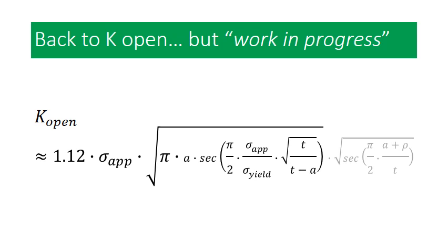Now, if you're familiar with my gamma exponent model, if you have a crack-like flaw, you're going to maximize your gamma exponent at 1, but if you have a corrosion flaw, a metal loss flaw, you're going to limit your gamma exponent to 1/2. So essentially what I've done here is show you where that 1/2 term comes from, and that all comes down to working through the math and assuming that you've got a lot of plastic zone, a lot of ductility in your material, you're kind of in a plastic collapse situation, and you've got a very small elastic ligament. And you can see that that elastic ligament makes the math work out fairly nicely.